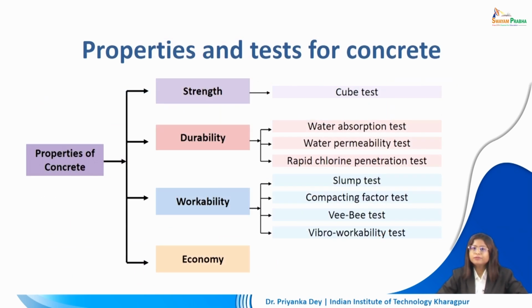When we are testing for the concrete, which is achieved by mixing our cement, fine and coarse aggregates and water at the right ratio, again reminding you that there is something called water cement ratio, which is the proportion at which we are mixing the water and cement. It has to be kept within a certain permissible limit. If it exceeds beyond that, it actually reduces the strength of the cement concrete.